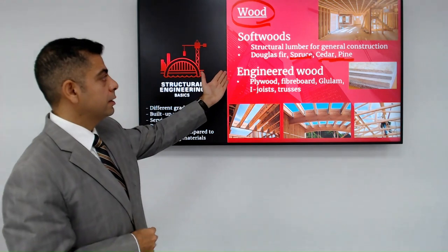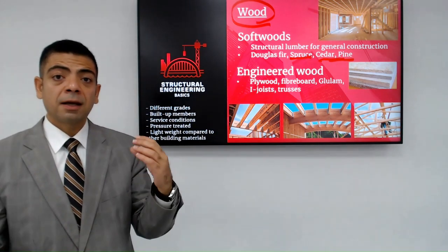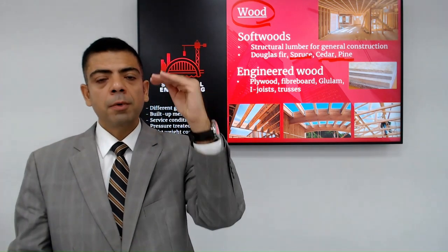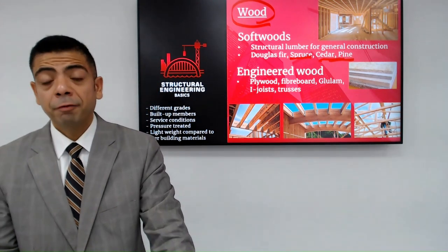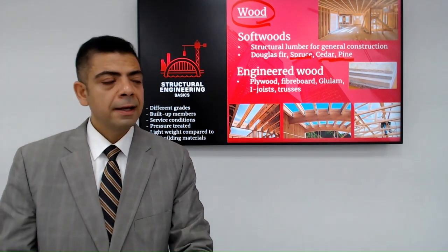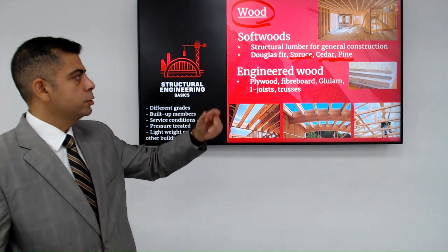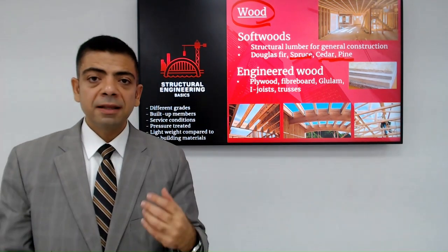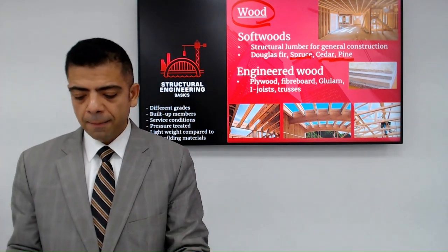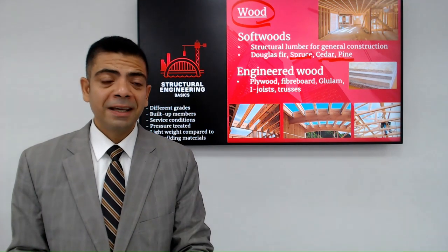Usually the fir, the Douglas fir, has the highest strength. If you're building a multi-story building, you will probably need the ground floor to have some sort of fir, Douglas fir, as part of it. I've used these different species and they have different strengths, and this absolutely needs to be taken into account.